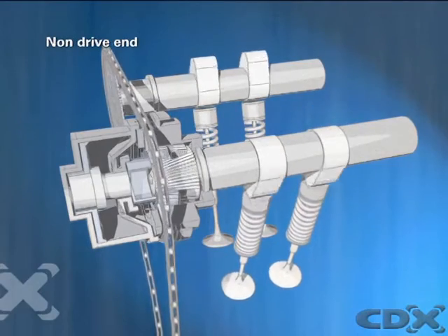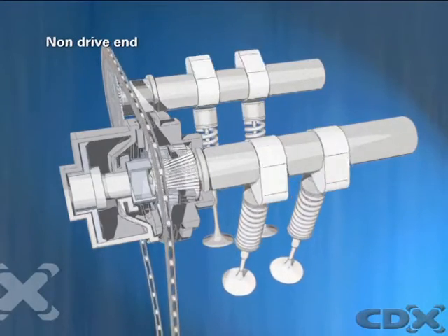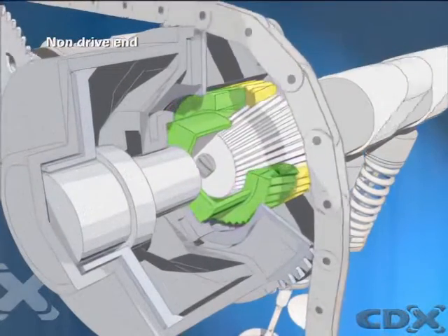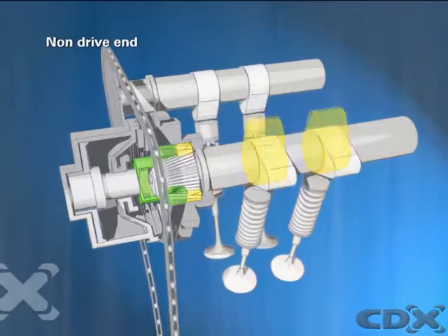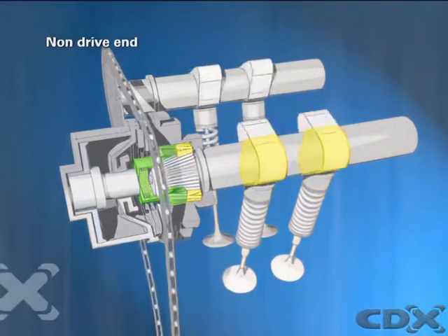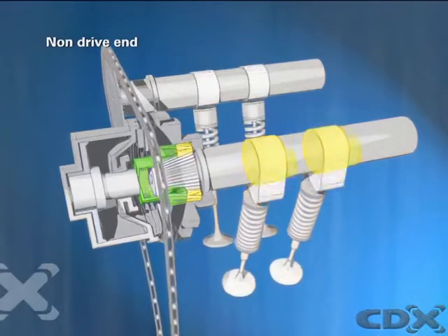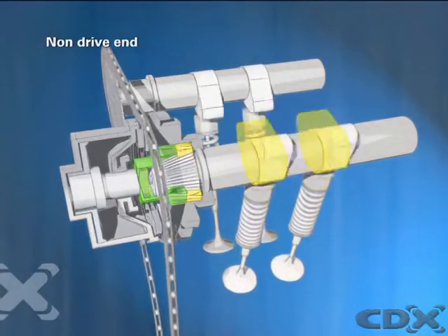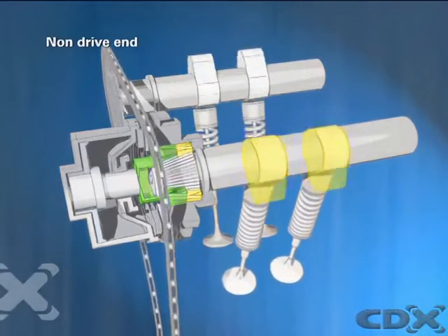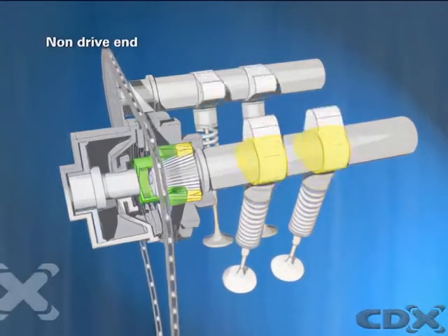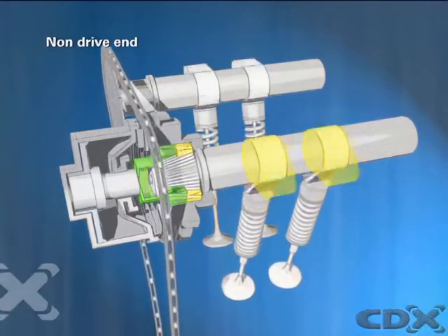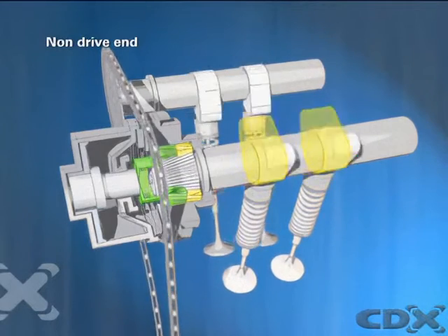Cam phasing VVT varies valve timing by shifting the phase angle of the camshaft. At high engine speeds, the inlet camshaft phasing can be rotated in advance to enable earlier intake, increasing the amount of valve overlap. This is controlled by the engine management system and actuated by hydraulic valve gears. Phasing change is either continuous or fixed.